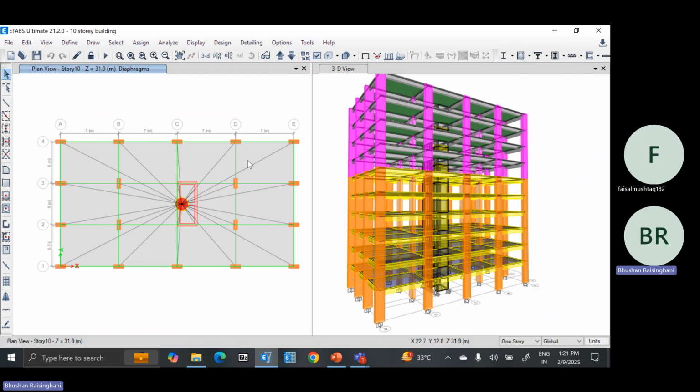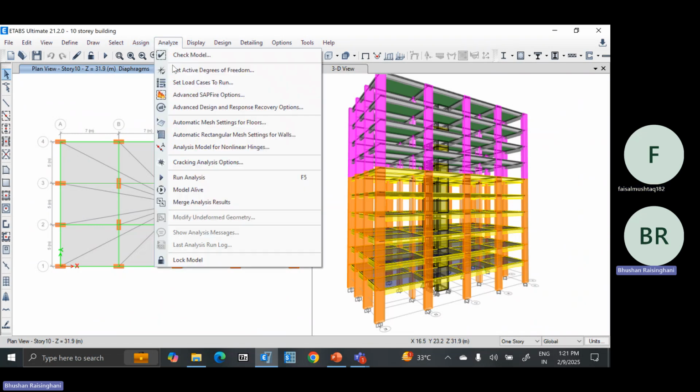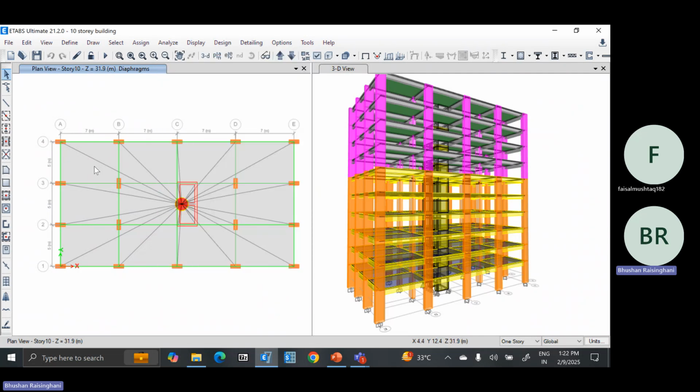Once those things are available, once you have analyzed everything, the next part is the meshing. We are using auto meshing in the floors if you are designing, and auto meshing in the walls. I will cover meshing separately. For analysis, you have to do the meshing as well. However, this auto meshing is a good option and it is not giving you separate results from previous models.